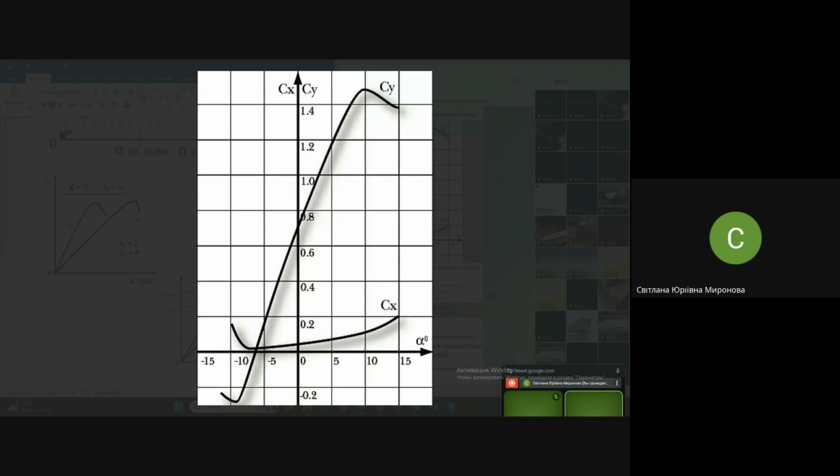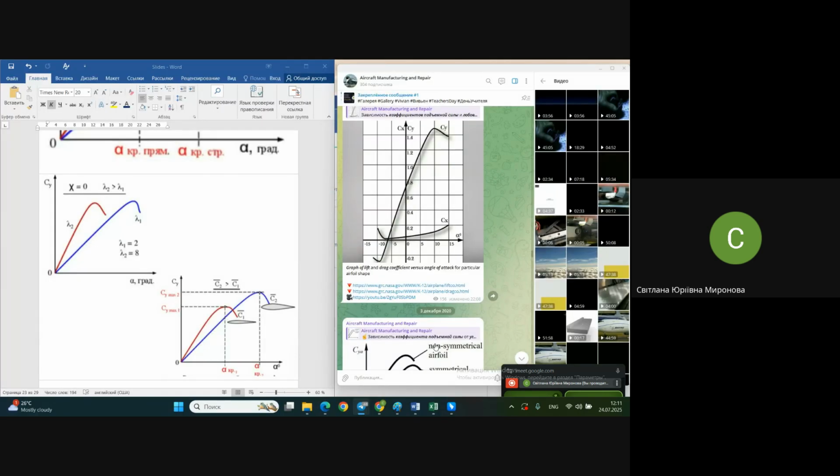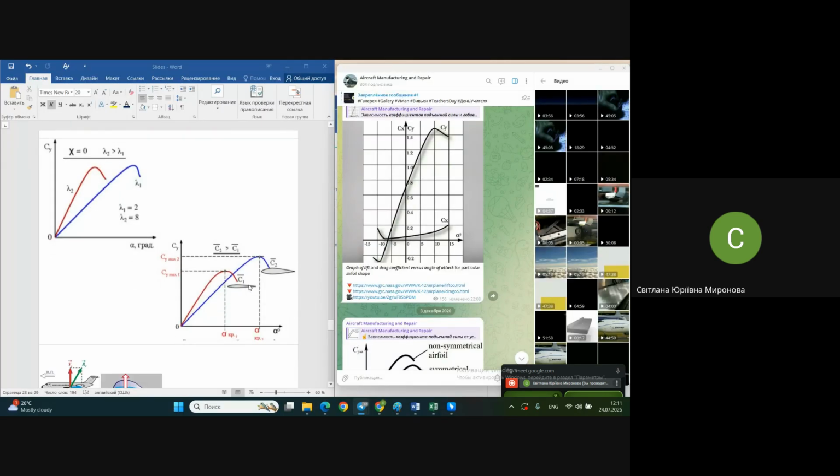position even of an airfoil on the same airplane, because I trust you've seen that airfoils, wings, let's say wing stabilizers, are usually not ideally horizontal in the airplane. They have some preliminary deviation from the horizontal line already, in order to use the characteristics of the airfoil in the maximum effective way during the flight.